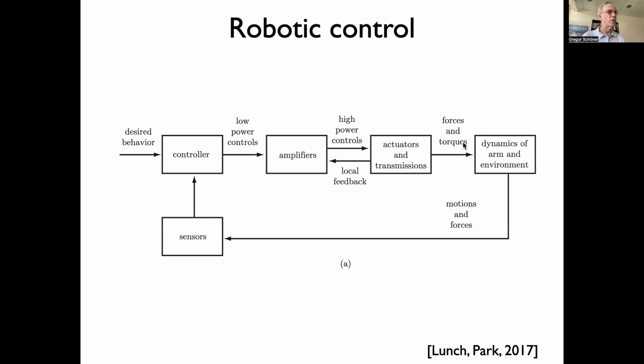In general, it could also be forces for linear actuators. So a lot of the control laws that we'll see actually compute torque. They say, I want a certain torque, because these models are based on knowing that when you have a torque, there's a function that tells you what kind of voltage or current to send to the amplifiers of that system. And that has very strongly framed how roboticists think about control.